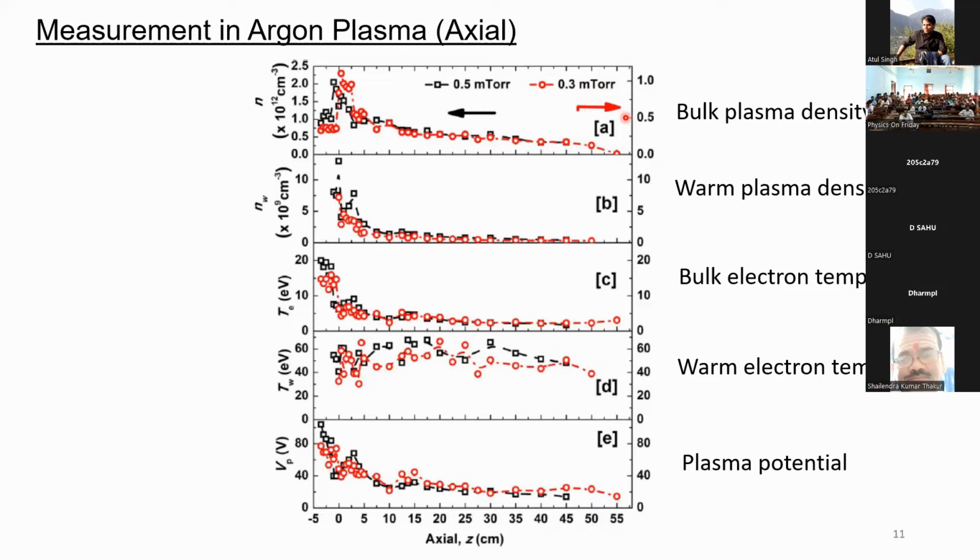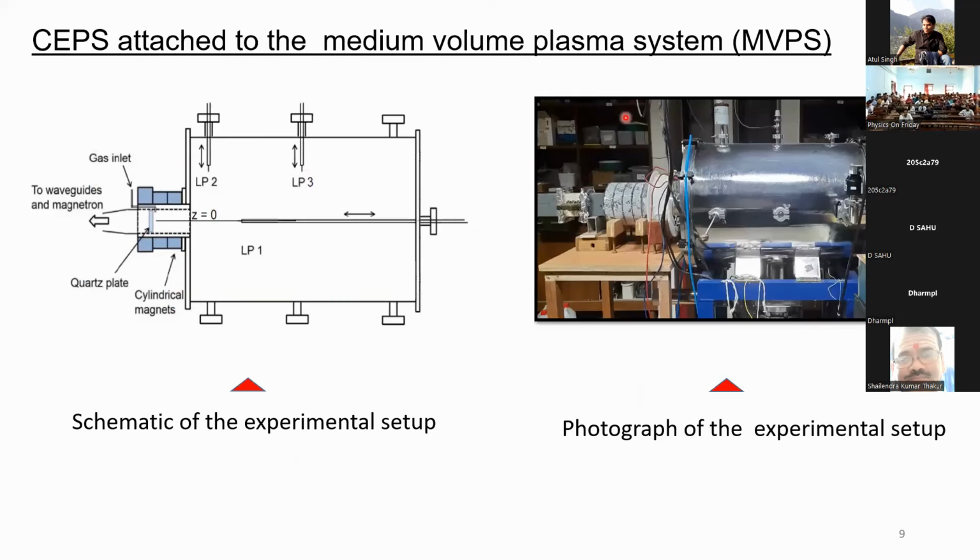What we generally do, whenever these systems are there, is attach a pump here. A two-stage pump is attached, so we evacuate the system. We switch the pump on and evacuate completely, so that the air, the nitrogen and oxygen, is completely removed. It goes down to 10 to the power minus 6 torr, from 760 torr.